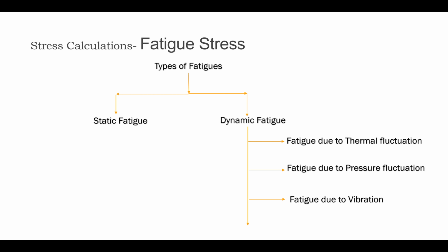Third one is fatigue due to vibration, and this vibration is because of FIV, flow induced vibration, AIV, acoustic induced vibration due to PSV pop-up, two-phase flow, slugging, rotating equipment, and low pressure and steam condensate lines. All these cause vibration in a piping system, and consequently create fatigue in the piping system. And the fourth one is fatigue due to wave motion, which is normally in offshore. It must be noted that the fatigue life of a material operated at elevated temperature may be reduced.